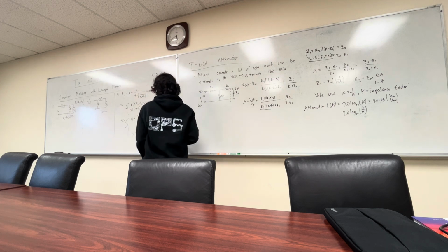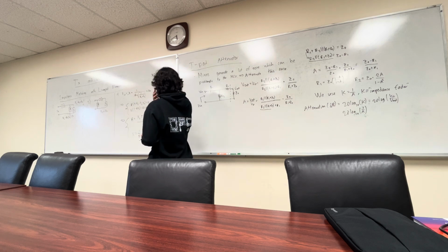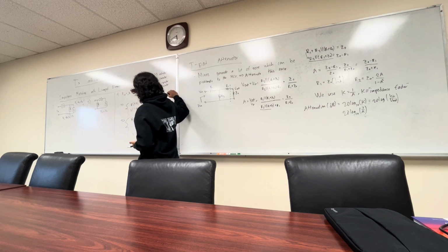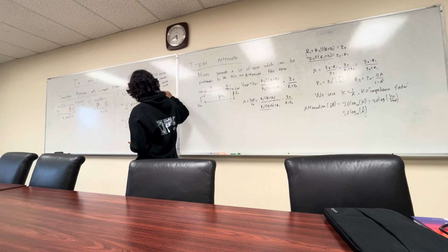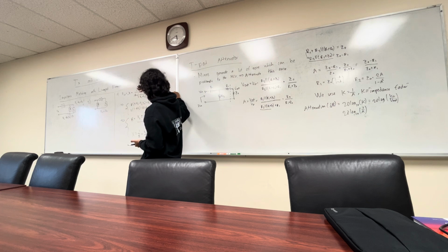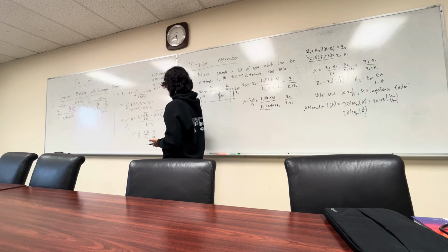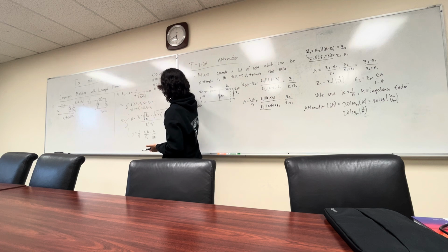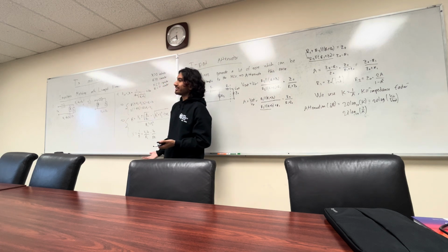Cool. So what this is telling you is, hey, if you have a certain system and you want to impedance match it, you have a Z naught and a ZL, you will pick your B and X values correspondingly. Kind of complicated, as you can see. But the good part about this is, like I said, if you know your characteristic impedance, you know your load. You can discretely solve for these two and from their signs figure out what element you need.